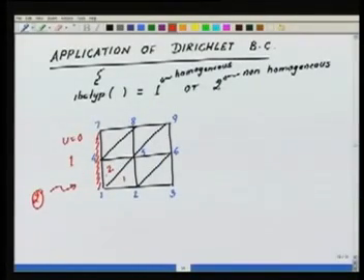So how do I identify those degrees of freedom? Easy. When we are finding the neighbors of the sides, when I go to element 2, for example, I find that the second edge of the element is sitting on the boundary segment 1. So I immediately know that for the boundary segment 1, the boundary condition is of a Dirichlet type, which is actually a homogeneous Dirichlet type. Sorry, it's not non-homogeneous, it should be 1. Boundary type should be 1.